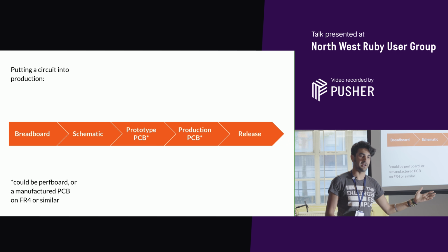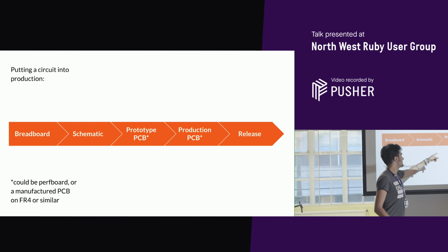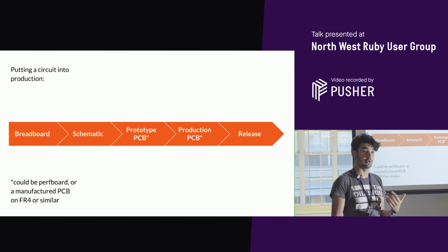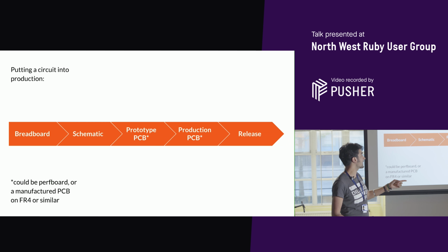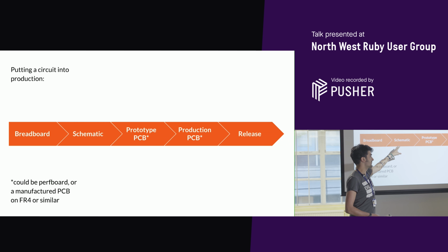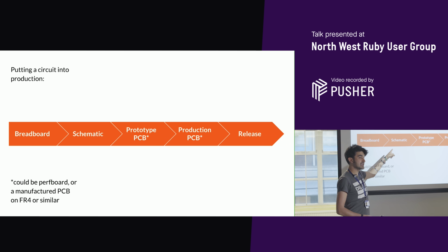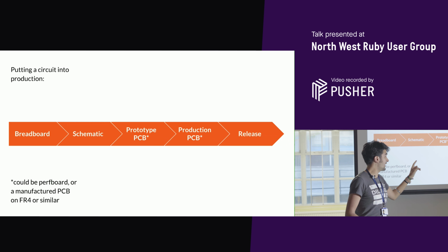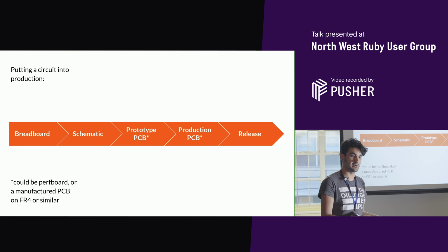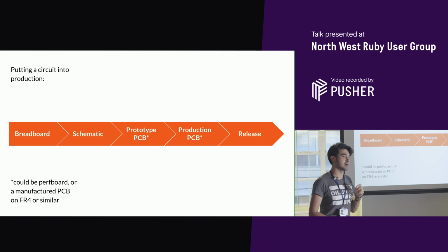And then maybe we refine it. But that final step, and in fact these individual steps here, could have a 6-week or more cycle between iterations. If something doesn't work, then I've got to redraw that. What's really interesting is this stage where I've had a completely valid schematic, and I've then got it made, got it manufactured, got it back, put the parts on it, soldered it all together to test it works, and it hasn't worked.